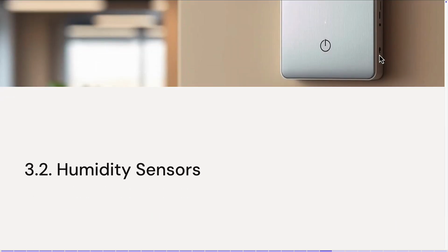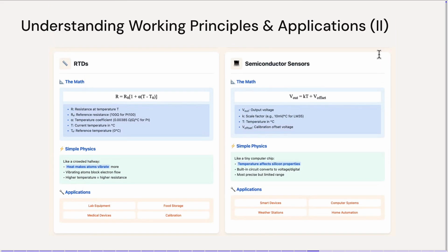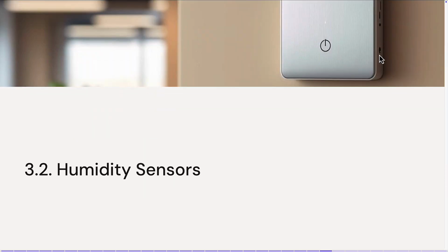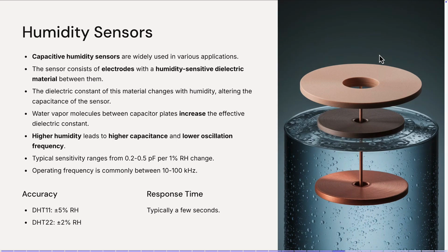Of course, if we needed to explain this formula, I would need a full course to go into every single physical detail and map it to the initial physics concepts. But this is not the scope of this lecture. This formula just captures the physical characteristics of these metals and how they respond to an external event. Now the humidity sensor doesn't work with resistance. This is a capacitive sensor, so we have a capacitance that will change when there is a wet condition or a dry condition.